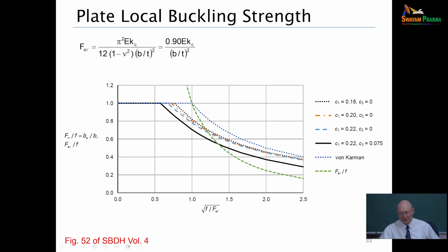All right. So you can see now what's going on here is basically Professor Winter recognized that you would get significant post-buckling strength with a plate, but only when it's very slender. So that's your curves out here. We've got significantly more strength, and still more than double out here at 2.5 than the theoretical elastic buckling strength.